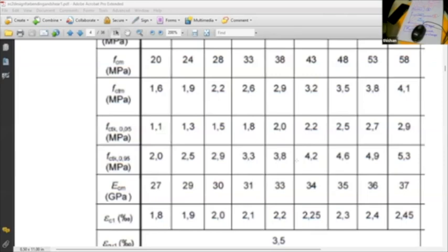Now suddenly you find you are even satisfying the 5-year return period on the wind-induced acceleration limits. And you find you have a much superior product. And that product improvement has come from the concrete technology that you have used, not by the design. Is that clear?